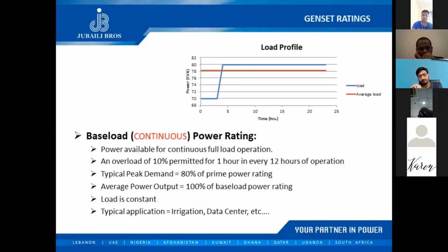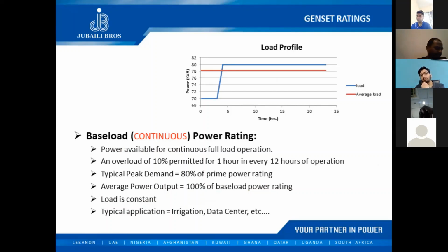Okay, last but not least, let's talk about continuous power ratings. I'd like to call continuous power ratings a simplified version of prime power ratings, because that's exactly what it is. In continuous power rating, the only difference is that my load is not variable. My load is fixed. My average over 24 hours should not exceed 80% of my prime power rating.